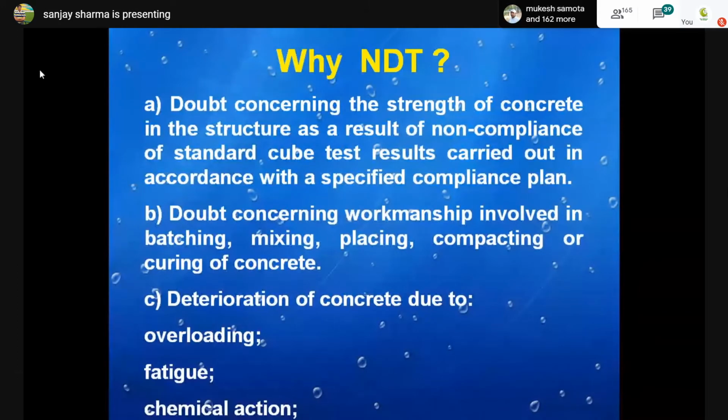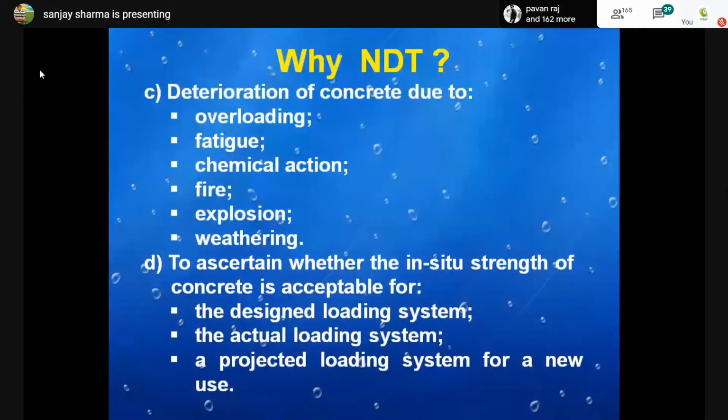With the passage of time, deterioration of the concrete occurs because of overloading, fatigue and chemical actions, and then fire, explosion, weathering, etc. So we have to ascertain whether in situ strength is acceptable for the designed loading system, for the actual loading system, and for a projected loading system for a new use.